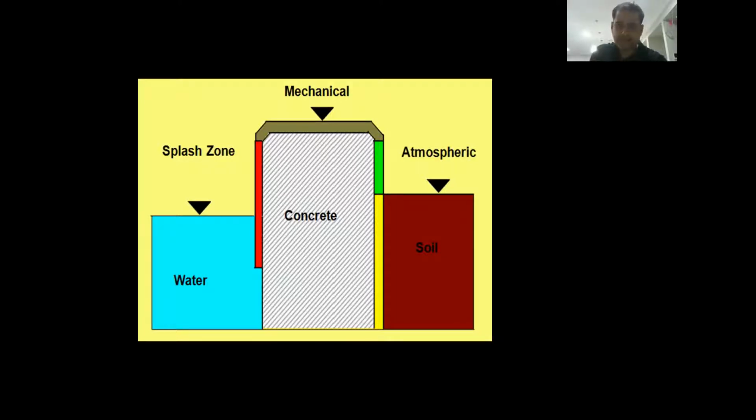attack on the concrete is coming from the tidal and splash zones, where you have cyclic wetting and drying of that particular structural element. And that would lead to very brisk corrosion rates because of that cyclic wetting and drying. That's why even in submerged zones, because of lack of oxygen, you don't have those brisk rates of corrosion.